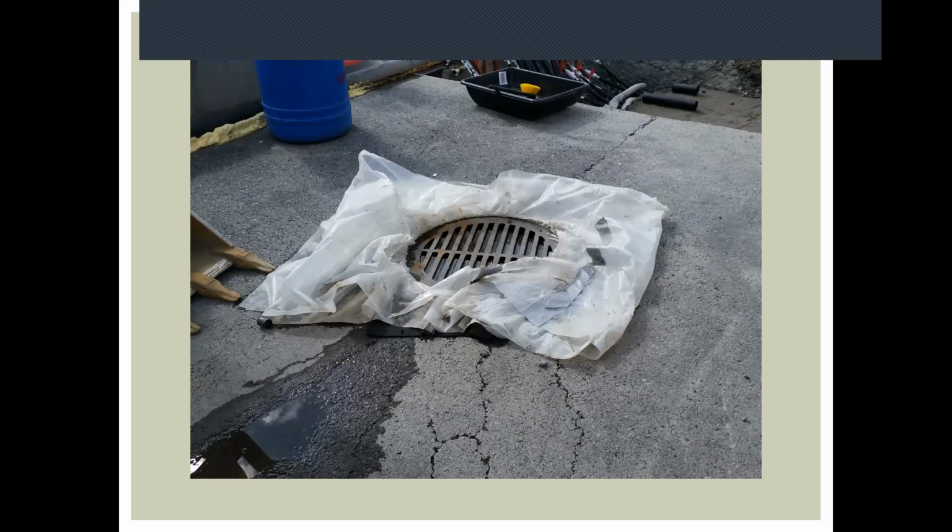I meant to put some slides in here on plugs, so I'll just mention briefly. If you're going to plug pipes, only use air plugs for maybe a day or two. They fail all the time. People don't check the air pressure. They get slow leaks. So a day or two on those. If you need to plug for a bit longer, maybe up to a week or so, mechanical plugs can work if they're installed properly. But anything longer than that, they really need to be grouted, grout the pipe shut to be taken out when the project's done.